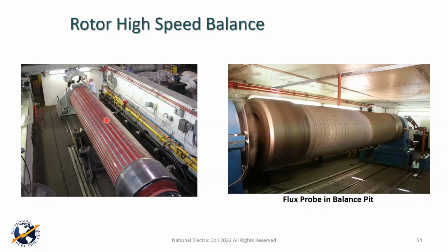And the way to do it, once you get it set up and everything's in order down here, and these trunnions obviously would be taken out of the way, they're just putting on the bearing caps down here at the end. But once they get everything assembled, they roll this thing out, get it normalized, make sure that all the force lube system and all the lift systems are all operational and been checked. The first thing they're going to try to do is run this thing up to overspeed, hold it for a minute, and come back down.